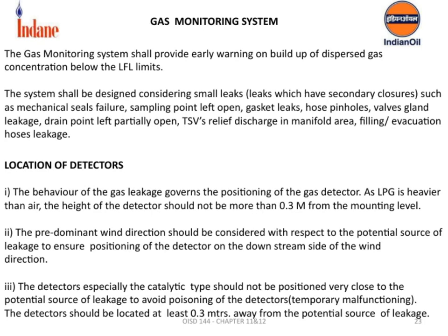Now, let's discuss the key considerations for the location of detectors as outlined in OISD 144, Chapter 11 and 12. First, the behavior of gas leakage is crucial in determining where to place the detectors. Since LPG is heavier than air, it's important that the detector is not mounted too high.